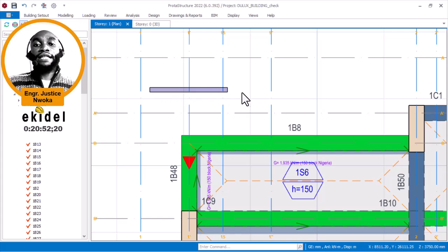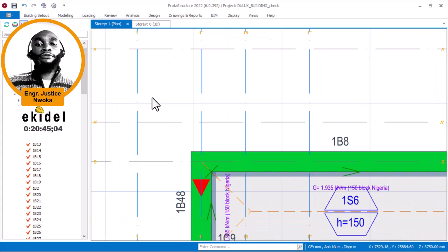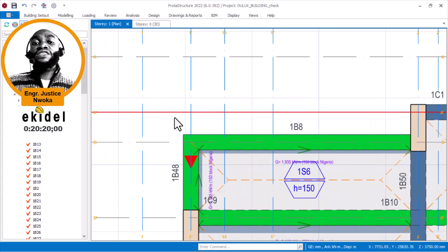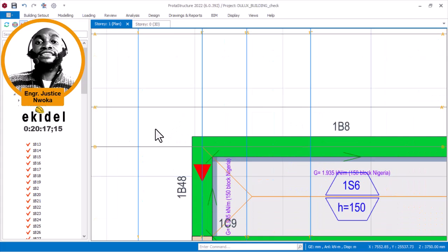Knowing that the diagram of a fixed end moment is something like this, if you have a beam like this, and then a support like this, a column, you can see that your diagram will go up something like this for a fixed end. It will come like this. Having this kind of curve on the moment means that here requires more top bar.